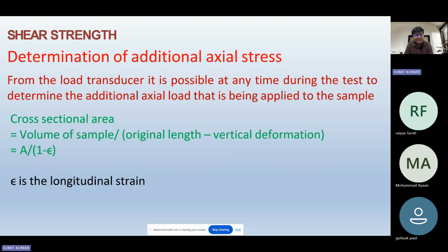that the shear strength parameters like C and phi can be calculated from the direct shear test, in which the normal stress and the shear stress at failure are known. We plot the graph with the x-axis as the normal stress and the vertical axis as the shear stress at failure. The graph intersects the y-axis; the value at the y-intercept is the cohesion, while its angle with the horizontal plane is the angle of internal friction. That value is known to us, but now what is the shear strength also needs to be calculated.